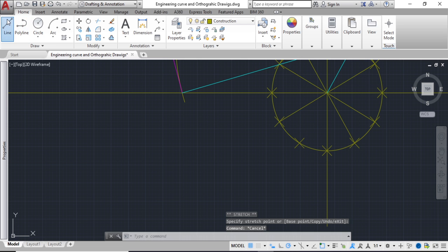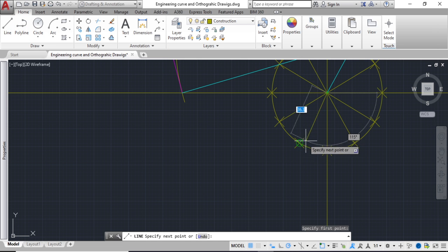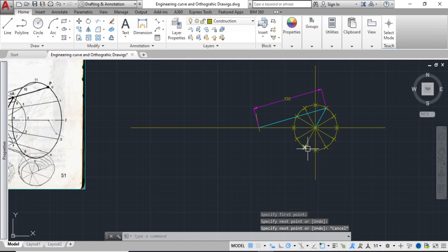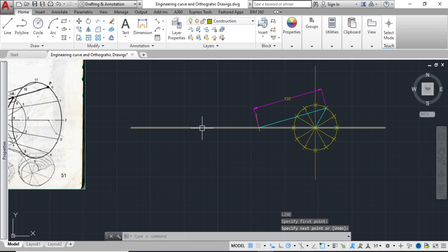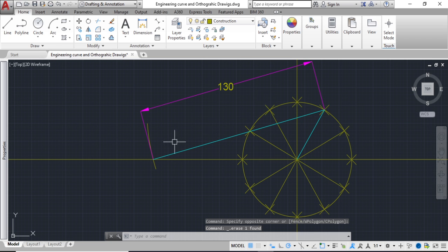Redraw this line here. Remember, escape, enter, escape to escape a command, and enter to re-enter the command so you get the draw line again. Enter, it goes away, enter, it comes back. Alright, good. Next thing we want to do is do the same thing for each of them.